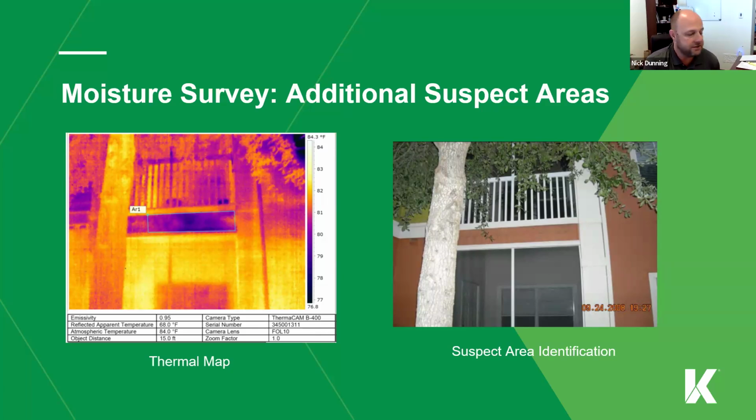And then also the ones that they sell that have mildewicide, all these different things within the paint, the mildew's not sticking to the paint anyway. It's sticking to the dirt that's on the paint. So mildewicide works great for about 3 or 4 months, and then it's essentially just typical paint. So really the best way to take care of your paint is to be on a good pressure washing schedule, and make sure it's maintained properly.